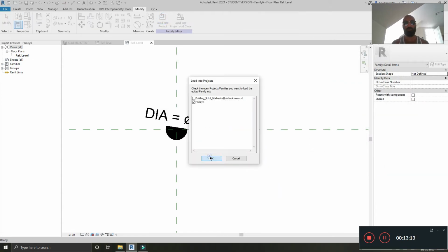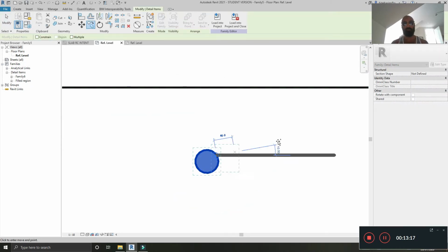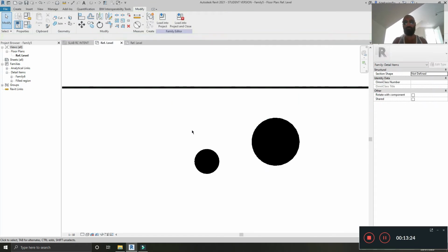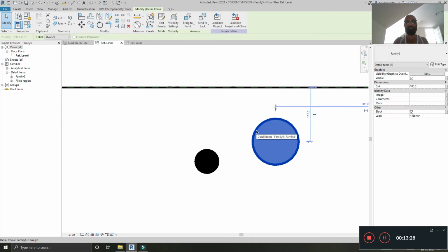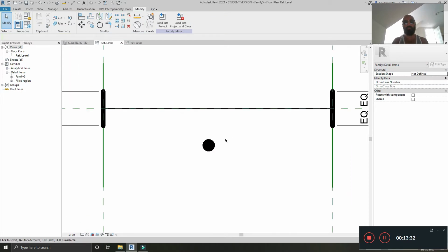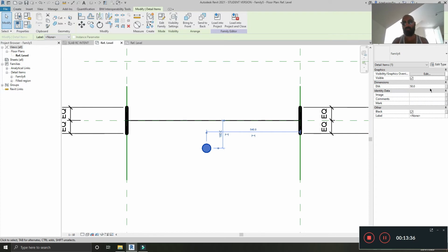If you don't know what an instance parameter is, it means that if I can have two of them in the same thing, have two different, let's say, well, for this case it's the diameter, two different parameters, instead of duplicating it and creating a new type. In this case we don't need to worry about that too much, but it's just nicer to have it there, editable there.